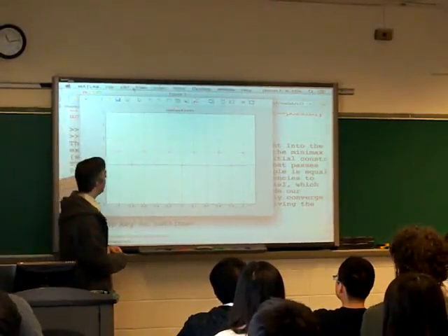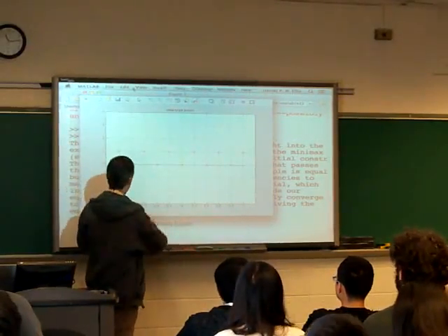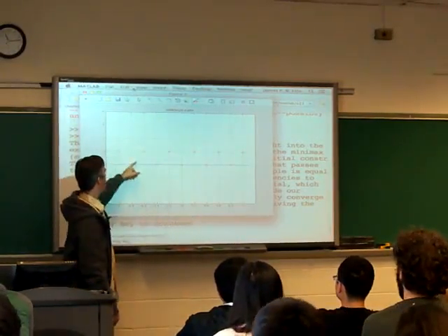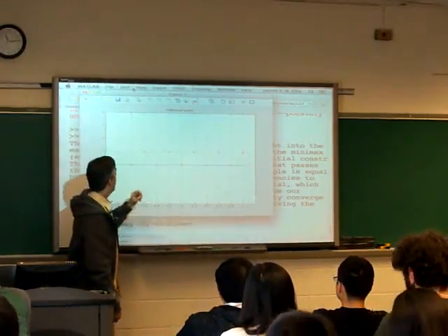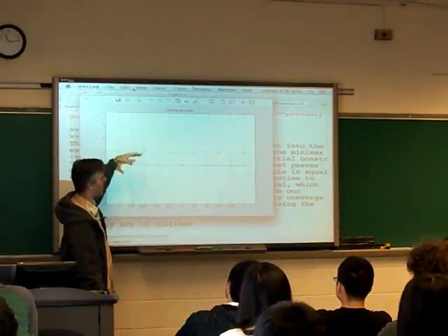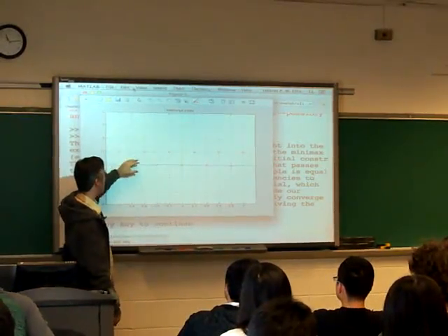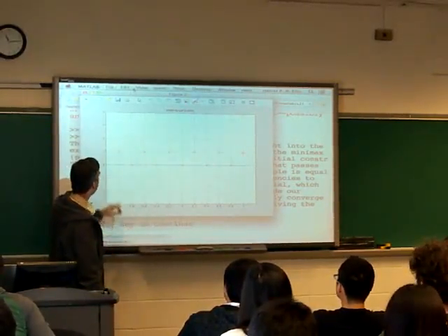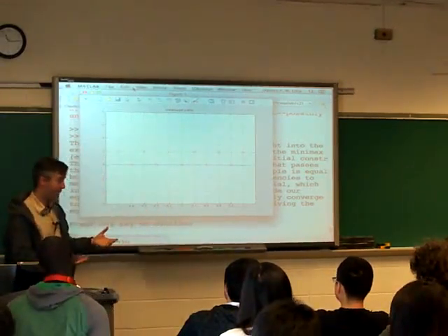So we're starting off, we're trying to find a filter, basically a polynomial which has equal-sized ripples in this interval from -1 to 1. And we're trying to find, in this case, 1, 2, 3, 4, 5, 6, 7, 8, 9, 10, 11 ripples. So we say, well, because we've just got a single kind of range here, let's assume that the ripples are between 0 and 1, and then we'll scale it later on to make it fit the actual depth that we need.